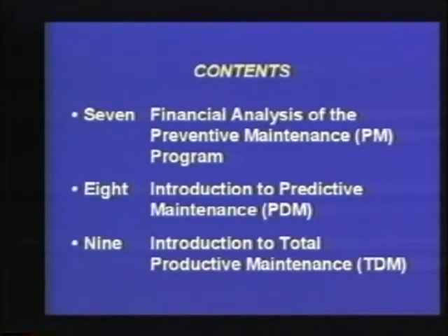In section 9, the last section, we'll address TPM, which is total productive maintenance, and that is, again, an additional enhancement of PM, where machine operators for, let's say, machines, or truck drivers for over-the-road vehicles, or forklift truck operators, and anyone else who is utilizing assets within the company to perform specific tasks, are given the opportunity to support the maintenance management program by actually performing some PM activities.